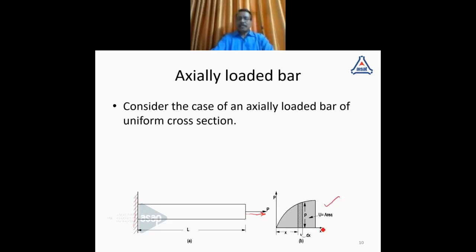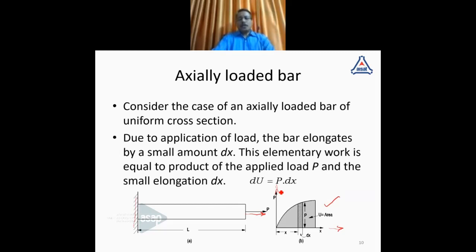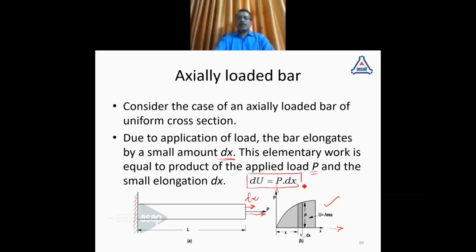The deflection or deformation is shown along the x-axis, and load is shown along the y-axis. And when you represent it like this, the deformation due to the application of load is, let it be dx. When the length is elongated by dx due to the load P, we can say dU equal to P into dx. And this is evident from this diagram also.